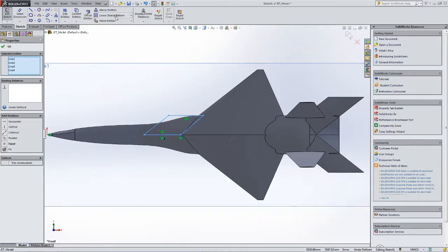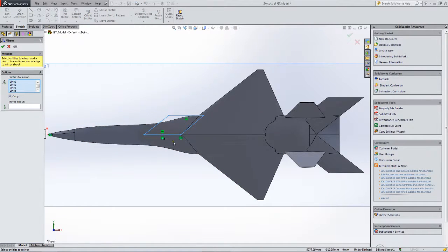Highlight, mirror entities. Over here in the dialog boxes, what you're doing is blue. And so while I was picking what lines I'm going to include in the mirror, that box was blue. Now I'm going to pick my mirror about point, and I pick that point. You see it gives me a preview of what I'm going to see in yellow, and I say yeah, and also there's a checkbox in the copy so I don't just mirror it and then lose the original.